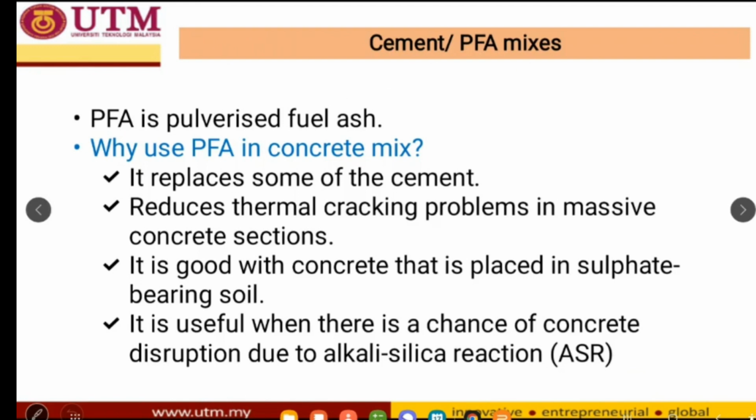All right, so we move on to the modified replacement method when we are adding PFA to our concrete. What actually is PFA? PFA is pulverized fuel ash. Why we use PFA in the concrete mix, we have already discussed before this in the admixture topic. Basically, it replaces some of the cement, and it reduces thermal cracking problems in massive concrete sections. It is also good for concrete that is placed in sulfate-bearing soil.